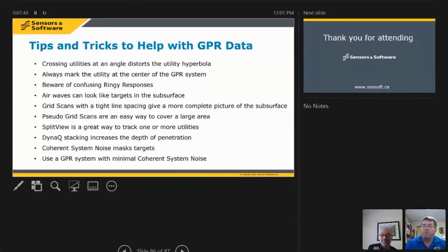Very good. Next question. What is the recommended procedure to make sure you stay online for long lines? And again, not varying from left to right. I always have orange cones available to me, like those 3 foot tall orange cones. And humans are pretty darn good at walking straight at an object if they have it in their vision. So you can put one of those things 100 feet away and say, walk straight towards that. And most people can do that, certainly with a bit of practice.